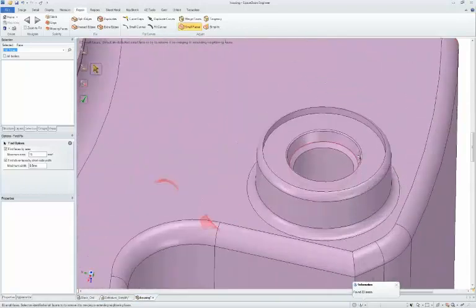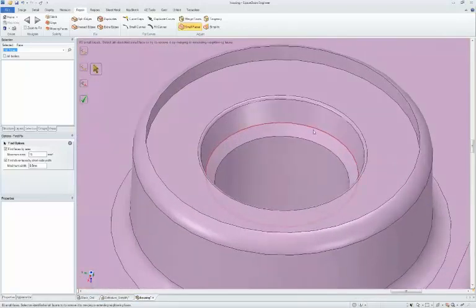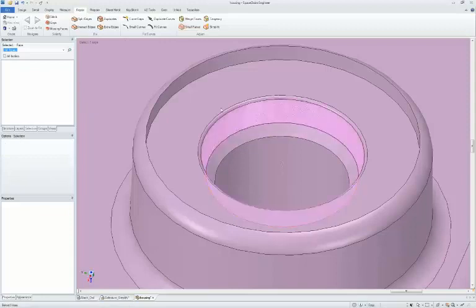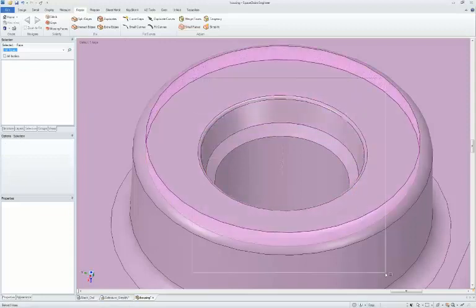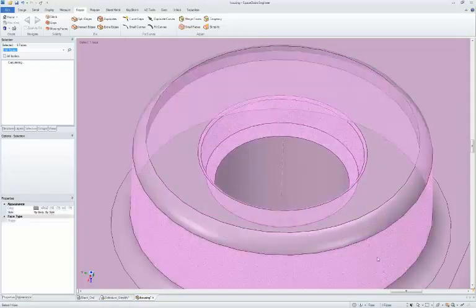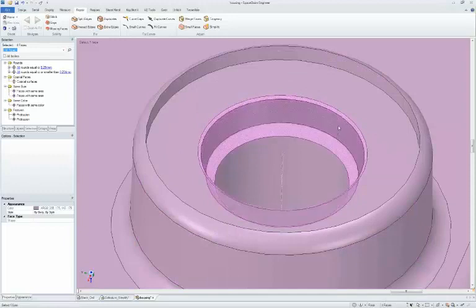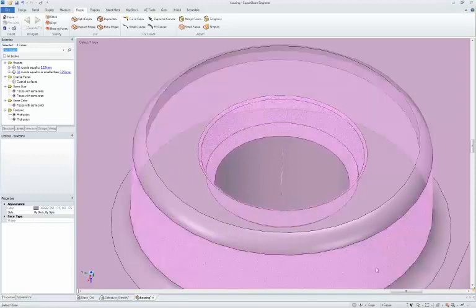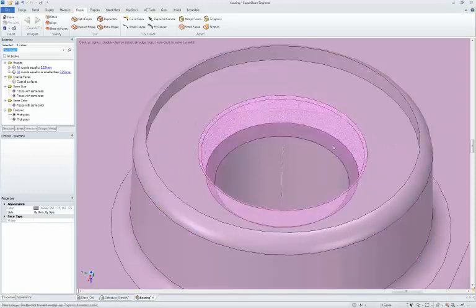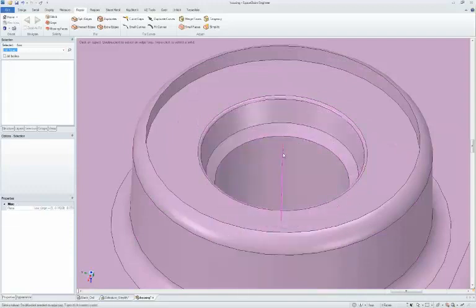This is a great example here. It looks like it's falsely identifying something here. Looks like there's a red area here. If I do a big box select, look in the bottom right-hand corner of my screen. How many faces do I have? It says I have 4 faces, even though it looks like I only have 3. That's because there's a really tiny sliver face that's there.